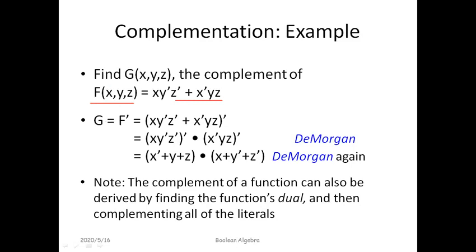So G is equal to f complement, equal to, we write down an expression for f, but then we have to invert everything. To proceed from inverting everything would require that we convert the plus to a dot, then we split the bar.